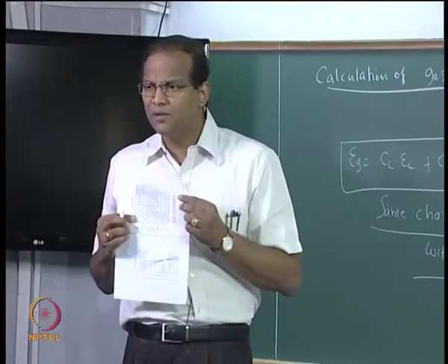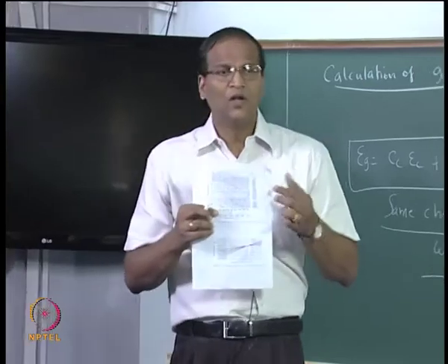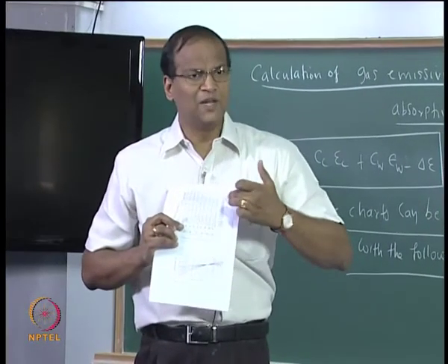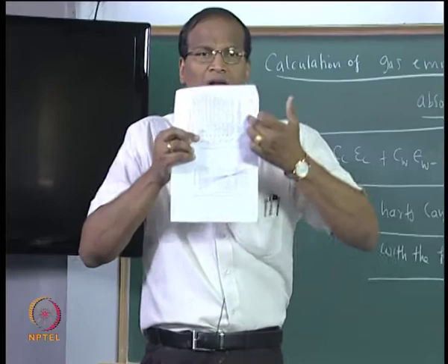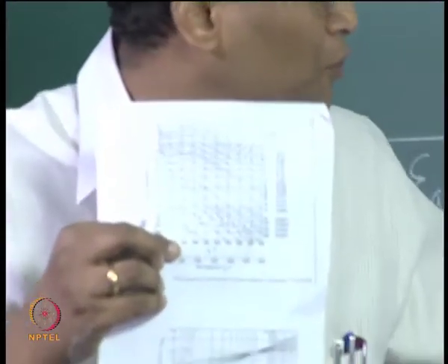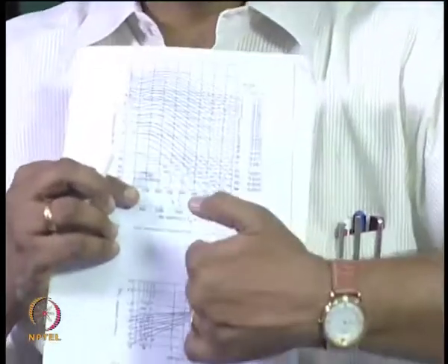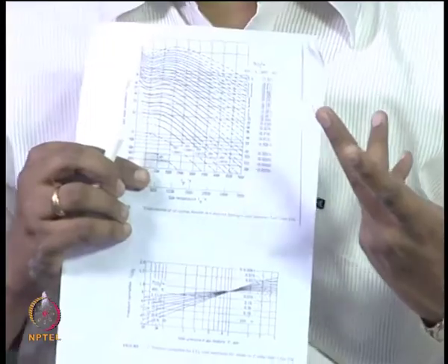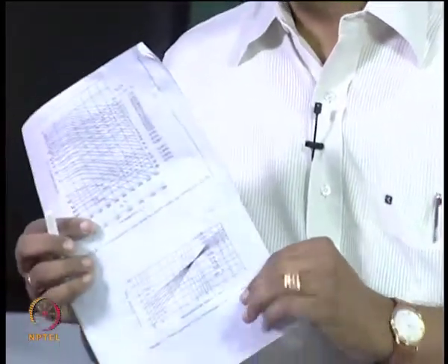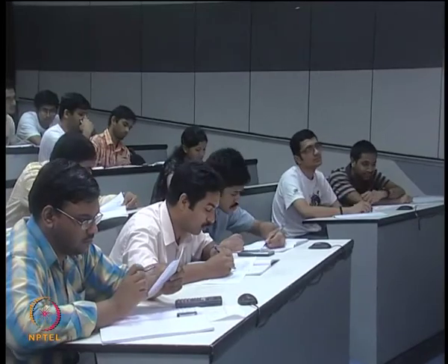You are not understanding me? See, this chart is tabulated in terms of Pc into Lm. Identify the Pc into Lm corresponding to 0.195 atmosphere meter. Follow that line and let it cut with the Tg 1400 Kelvin. Right side ATM meter is also given. Please look at the chart carefully.